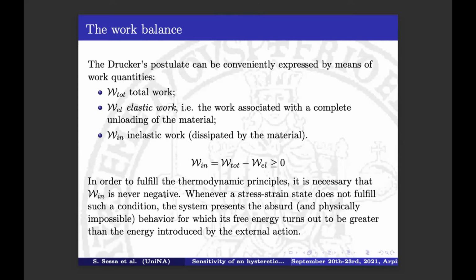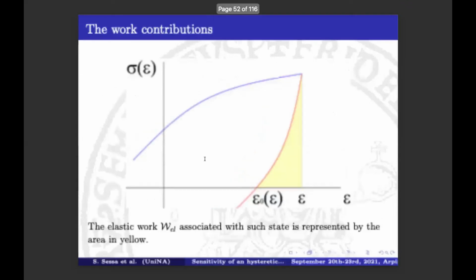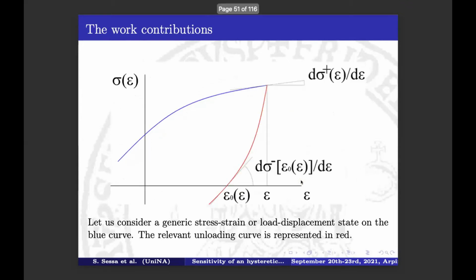We must actually verify this condition. This is not always satisfied by phenomenological materials, because it is not trivial that this quantity is non-negative. This figure represents the elastic work, the one that I called elastic, and is associated with the generic stress-strain equilibrium state. Stress-strain or load-displacement is the same thing.